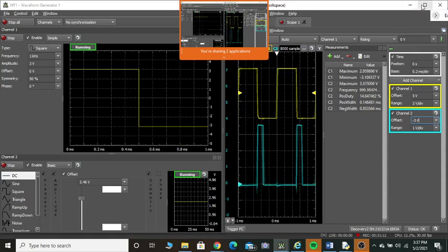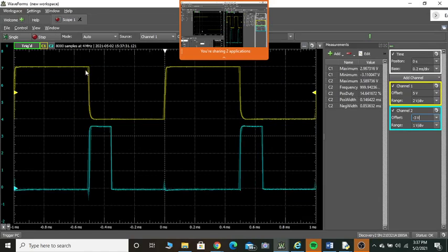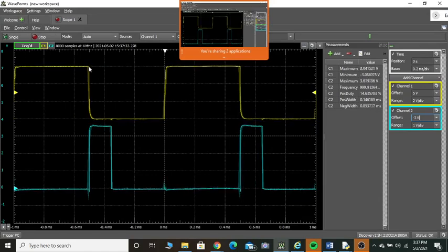So what do I do now? See now, is this your trigger signal LO1? And when LO1 goes down, this will become the trigger signal. Can you see this is now in the quasi-stable state? It is in the quasi-stable state depending on the value of control voltage, the value of RT, and the value of CT. Correct? And once the quasi-stable state ends, it goes to the stable state.